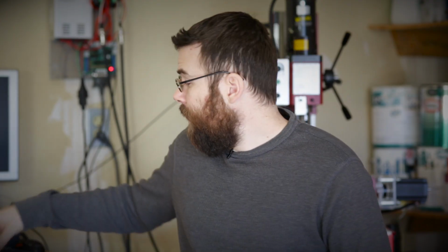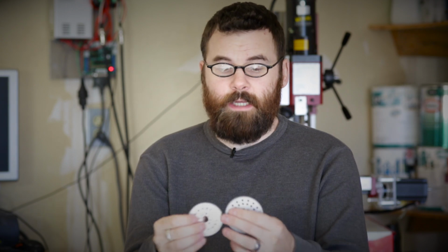So gears can be very useful when the motor is relatively close to the output drive shaft, because they have to be relatively close to one another. That is one of the pros for using gears. However, because you have a solid contact point between the two, they're very robust, very reliable, and not very prone to breakage, unlike a belt or a chain which could snap or come off.